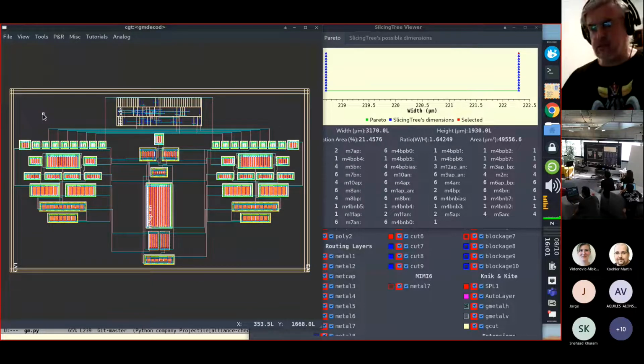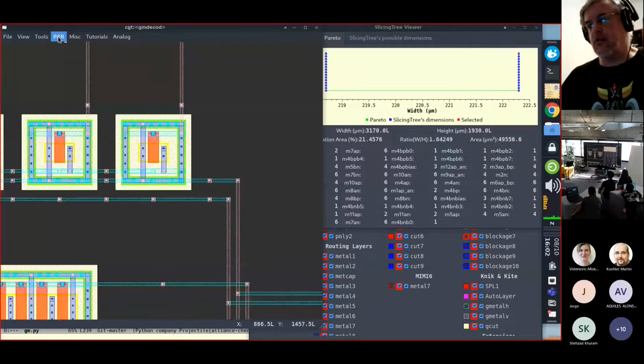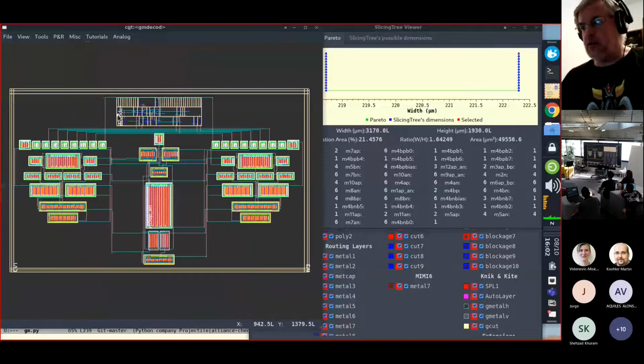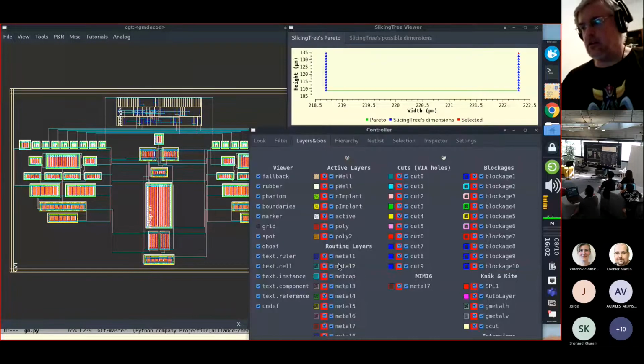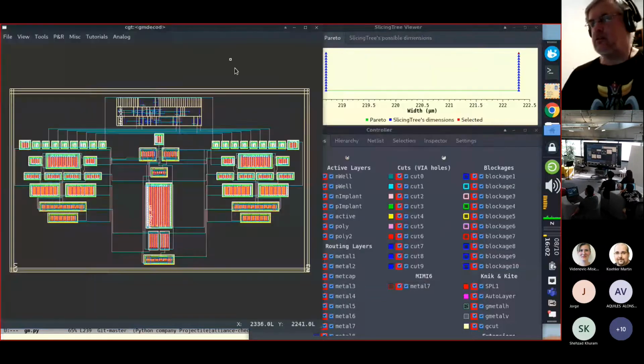And those little bumps here are artifacts that stay only because the global routing, the detailed routing is still active. To make them disappear, it's quite easy. It's just finalize routing and then they are gone. They are only metal 2 remaining. Okay. So I think this will be all for my presentation.